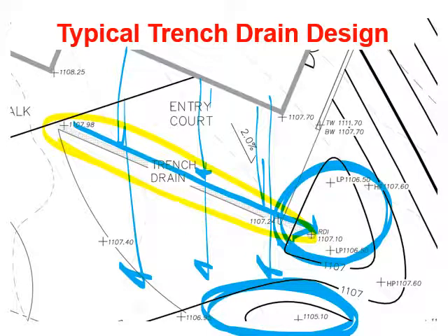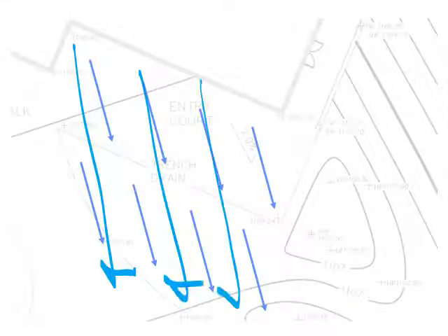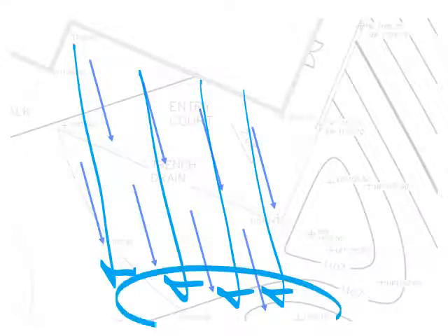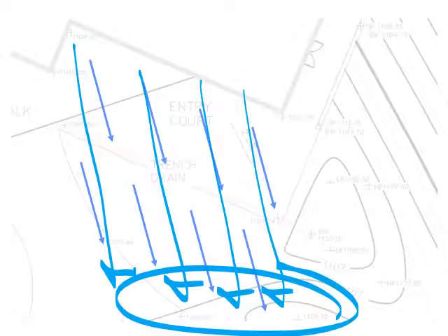retention area. This is something you're going to use in your entry court plazas and possibly in your parking lots as well if necessary, but mostly in your entry court plazas in order to break the drainage areas into smaller sub-drainage areas. So again, we have faded out the drawing and we're going to show you exactly how this works. As I said to begin with, we've got water just sheeting off of this paving area, and we're getting a large quantity of water down at the bottom.